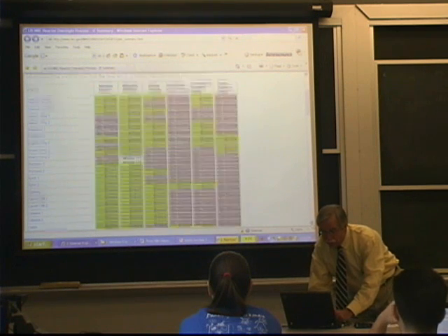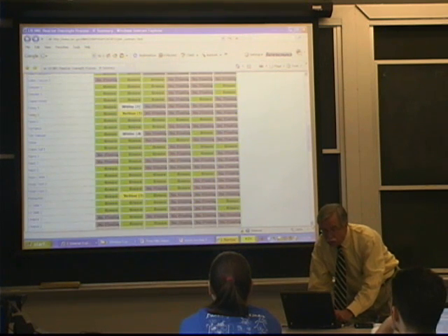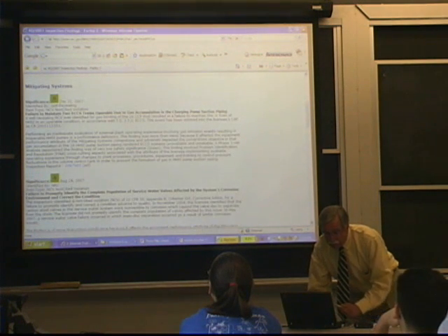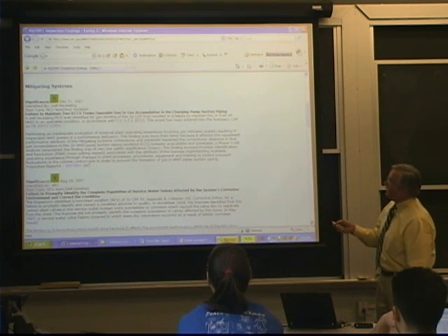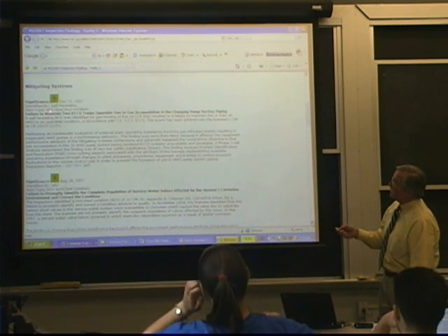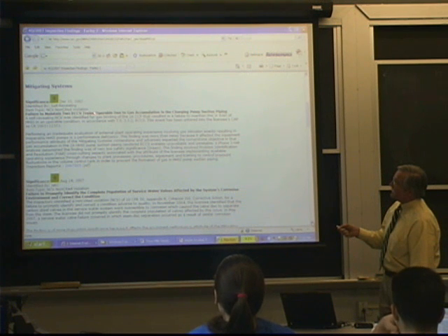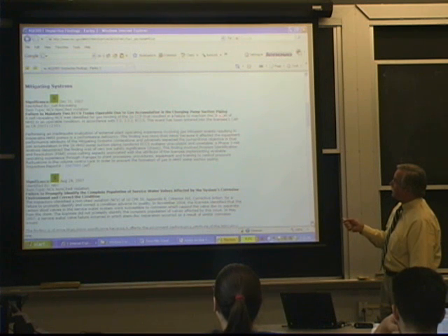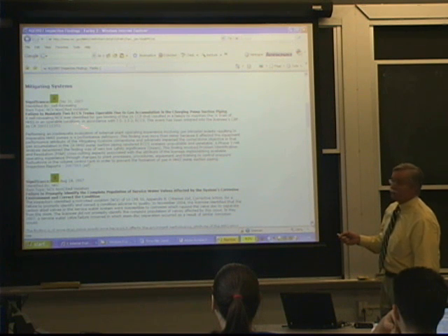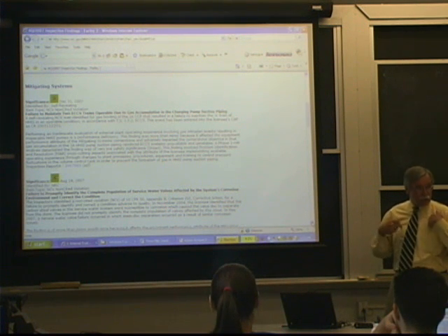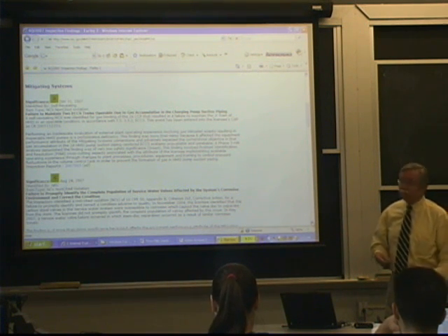Let's go see if we can find a yellow. Farley 2. What happened there? But you can see, even though they have green, they have what you call non-cited violations. Failure to maintain 2 ECCS trains operable due to gas accumulation in the charging pump suction line. Self-identified. If you identify it by yourself, you get credit.